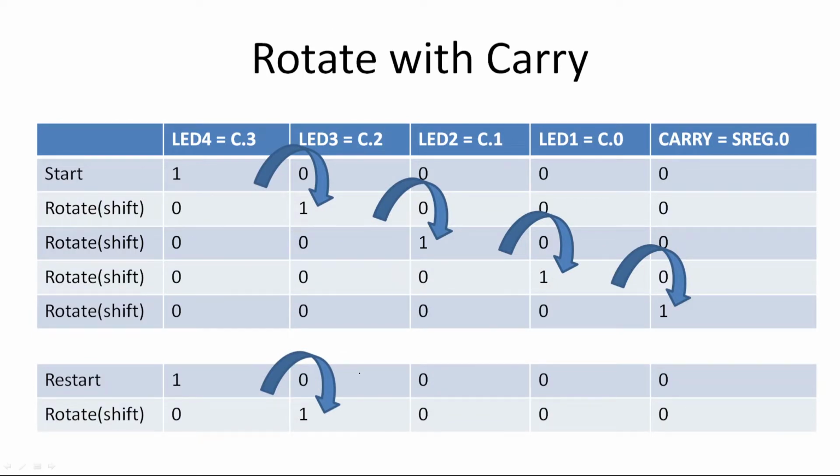This is rotate with carry. Let me understand. So we are going to move a value of 1 from LED 4 to 3 to 2 to 1. And if it carries, I'm going to reset and restart the whole sequence again and carry on and carry on.